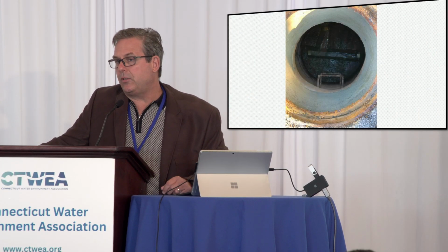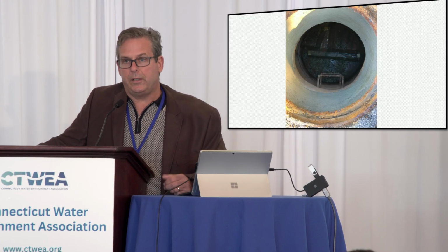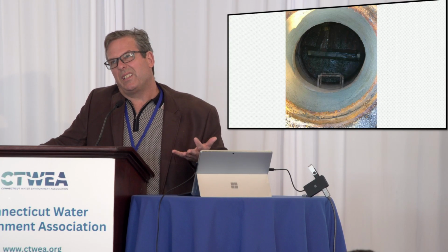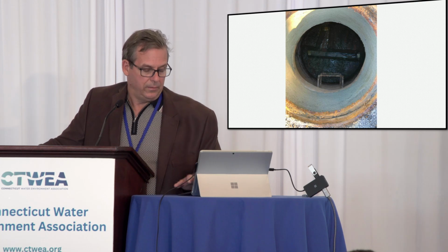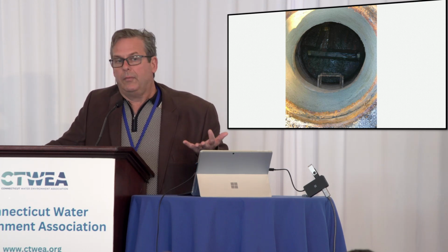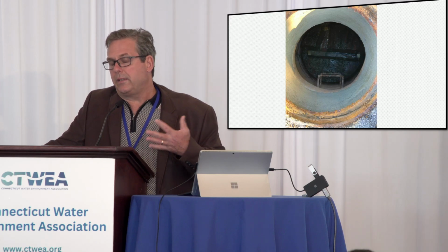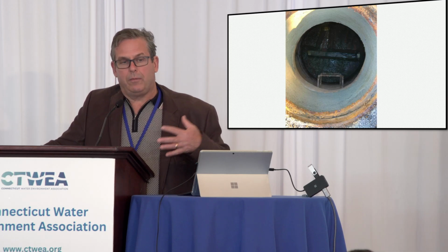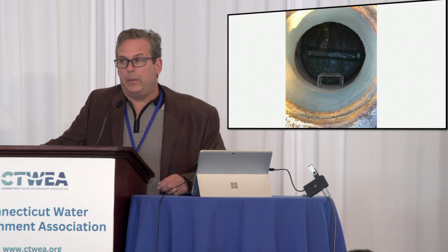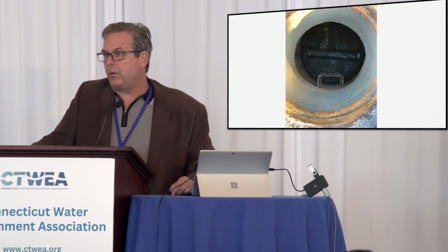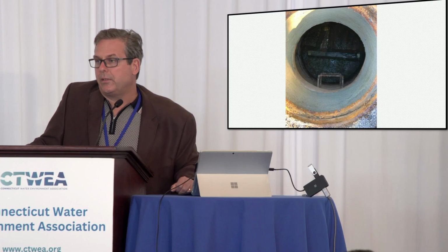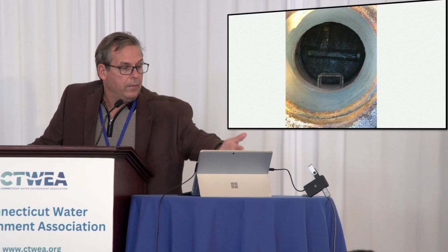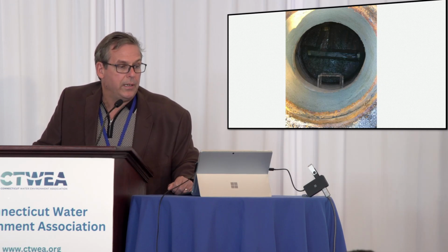Me and my guys did this. You just need a mason brush, water, and a mortar pan. Over the last couple of months, we've done 55 manholes like this. But for a small team, that's a lot of work, and if you don't have a separate collection system team, you have to integrate it into your workload. We just made this sort of a new thing that we do, and then when we have windows of opportunity, we might focus 2 or 3 days where it only needs 2 guys to be there, unless it's on a high traffic road, then we would need some traffic control. But again, that should last a long time.